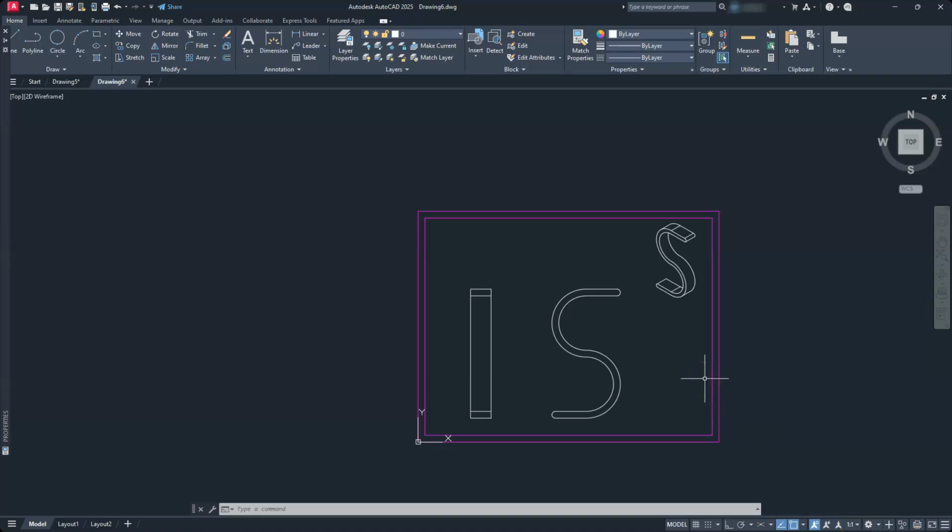If I don't have that option, I can also do this a manual way. The first thing I always do is type in LTS, hit enter, and set that number equal to whatever my scale factor is, which is 20 in this case. You should see your hidden lines or center lines or any other kind of lines approach and adjust themselves to the appropriate setting, or what they should be. All right. Next thing we're going to do is start adjusting to our center lines, right? So before I do that, I'm going to use the command called CLAYER. Hit the enter button, and then I have to tell it what layer I want it to use. In this case, it's going to be called center. So CEN, hit enter. So that's set to that, right?